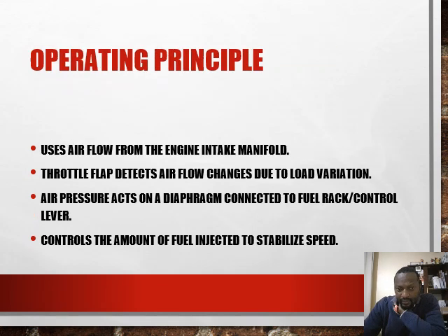Now, the operating principle is that we talked of pressure difference. This governor will use the airflow from the engine intake manifold. And as the throttle flap is closed and opened, the airflow varies, and this changes the depression that is created in the venturi unit.